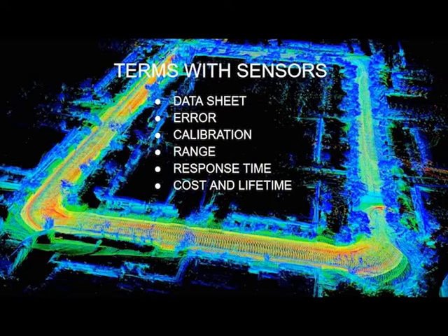Firstly, zero error, where the error is due to not having a proper zero reference. Secondly, the errors occur due to the change in operating range of the process. Lastly, the errors may also occur due to the mechanical wear and tear of the sensors over time.